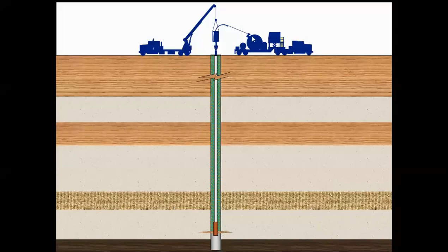Then you will pump a sand laden fluid into your coil. Now this sand laden fluid will be slightly different. This sand can be a natural, naturally occurring sand. It may not be a sorted sand, because you just need to make the cuts in the casing and in the cement to establish communication with the reservoir.